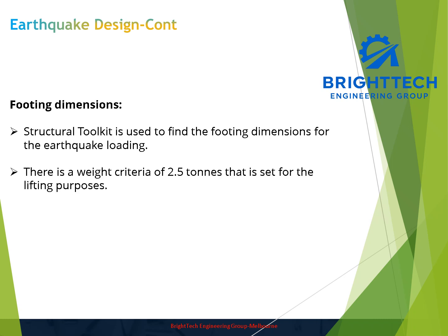Footing dimension. In order to design the footing, we adopted the structural toolkit. It helps to find the footing dimension. There is a weight criteria of 2.5 tons that is set for the lifting purposes. As we already mentioned, it's going to be precast concrete footing.